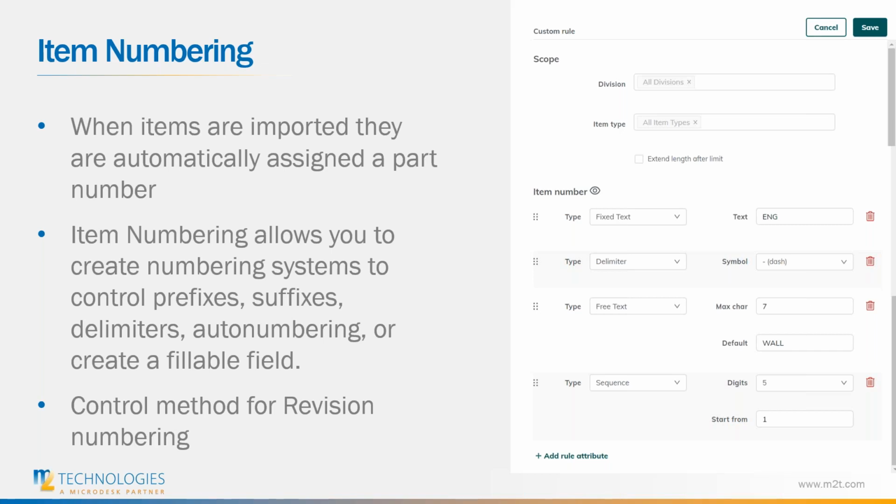settings. So within Upchain, by default, it is going to have all items as they are brought in assigned a standardized number. These will run in order sequentially, and the basic will have standardized digit count and prefixes, but we're able to go back into our settings and change these prefixes and sequences in order to customize that numbering system to our use. So we have a few different ways we can do this.